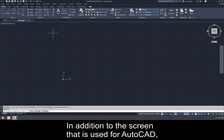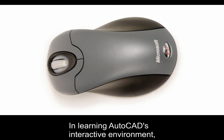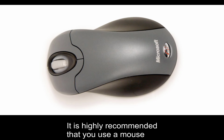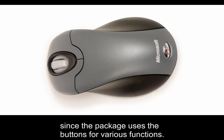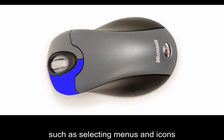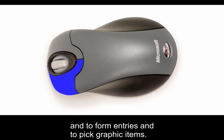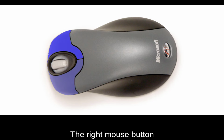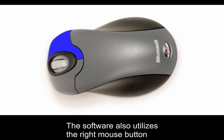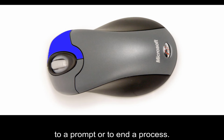In addition to the screen that is used for AutoCAD, the mouse is utilized extensively. In learning AutoCAD's interactive environment, it's important to understand the basic functions of the mouse buttons. It is highly recommended that you use a mouse or a tablet with AutoCAD since the package uses the buttons for various functions. The left mouse button is used for most operations, such as selecting menus and icons or picking graphic entities. One click of the button is used to select icon menus and to form entries and to pick graphic items. The right mouse button is used to bring up additional available options. The software also utilizes the right mouse button the same as the Enter key and is often used to accept the default setting to a prompt or to end a process.